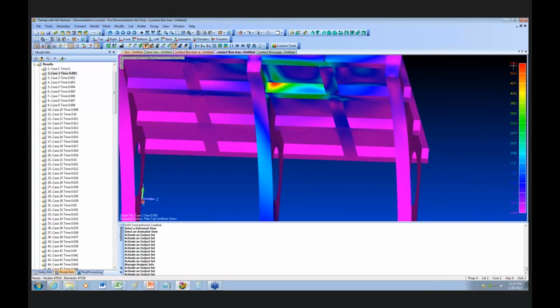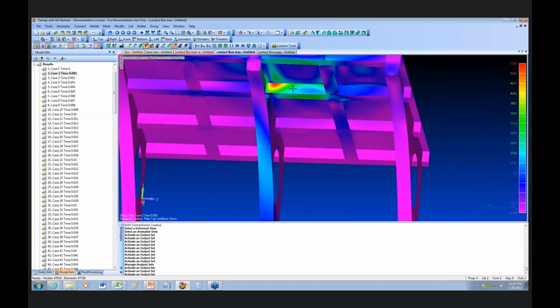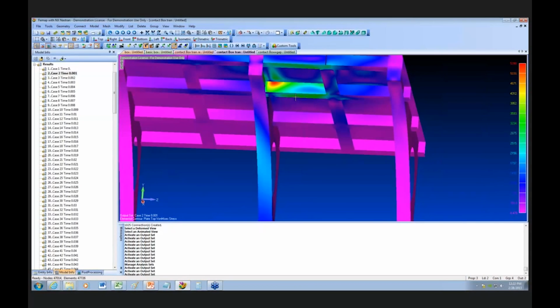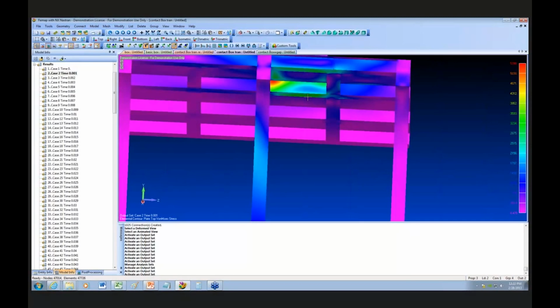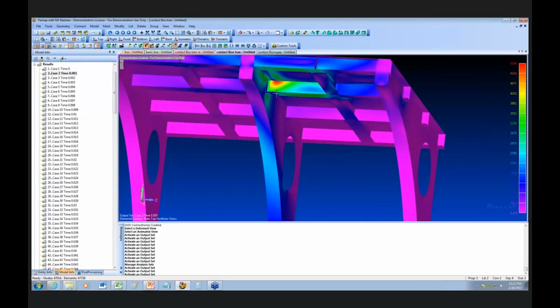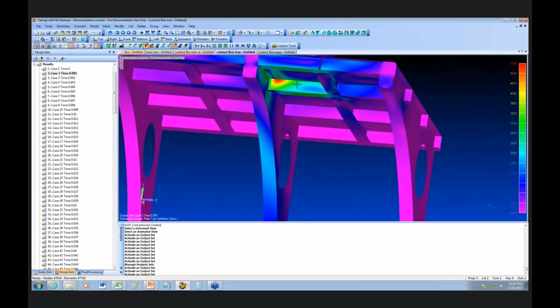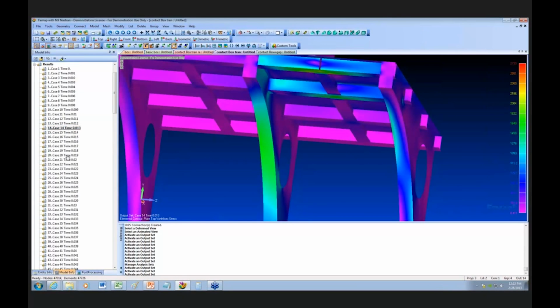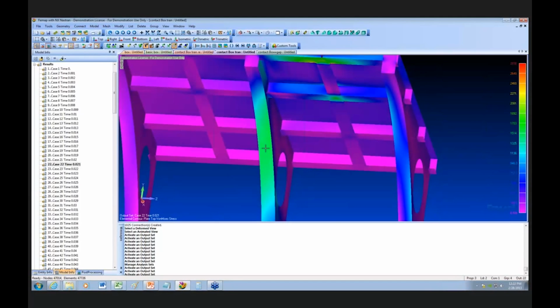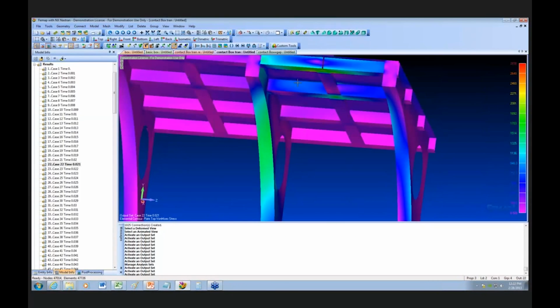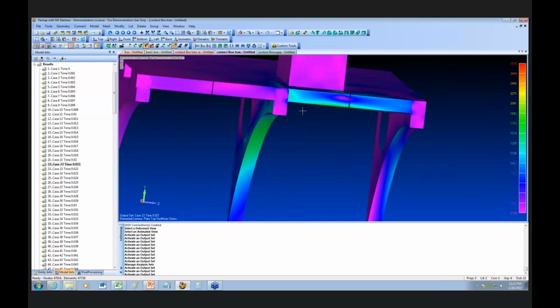So I'm getting the high peak stress right in here. It's really not high, 53.5 KSI. It's really not bad. But you can see the high stress is probably higher here because it's a lot stiffer right here. And so this is the high stress. This is right at impact. And as I come down through this thing, we can see that the stress starts dissipating out, and you start seeing the high stresses over in here and over here, and these stresses will be lower, and that's your typical impact. Okay, and so this is with a transient, and it actually didn't do that bad of a job.